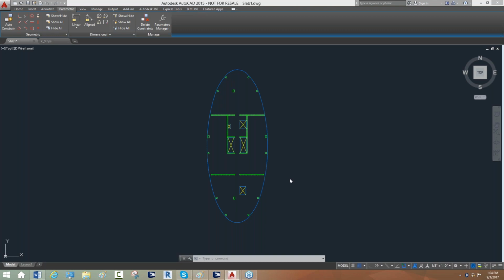And then we want to look at the recycler screen. The recycler screen is really where the user has the ability to modify, manipulate the program's answer or solution. And sometimes the program doesn't come out with the optimal solution. You might have, for example, multiple spans where the two end spans require more force, and you have a chance to optimize where you have added tendons placed on those two outer spans, and we're going to go through that